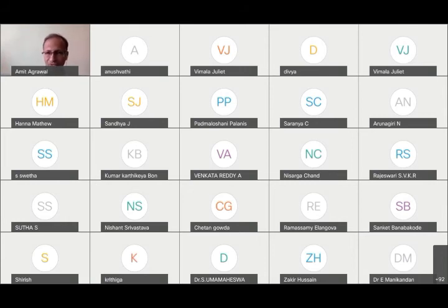Okay, and of course, you can see that going from here to here is a focusing, just like in optics we have focusing. And this is a hydrodynamic focusing which is happening. This focusing is being facilitated by two side streams, which have much higher momentum, and therefore they are able to compress this main stream into a thinner part. So we will call this hydrodynamic focusing.